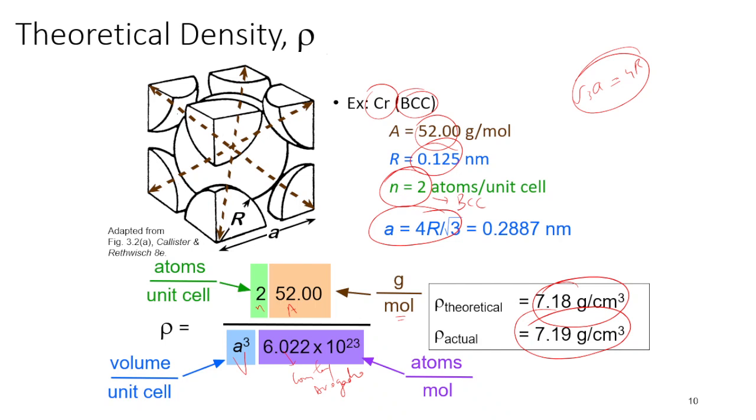There sometimes the value could be similar to each other, so there could be a clash. So we cannot entirely find what material it is just from the density alone. So usually the technique is, as I mentioned earlier, through X-ray diffraction and energy dispersive spectroscopy.